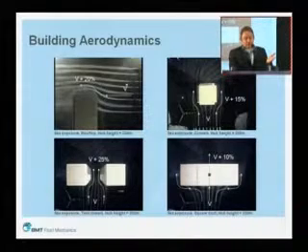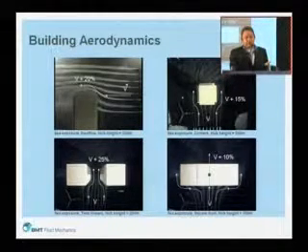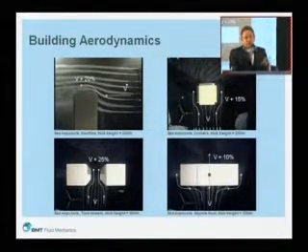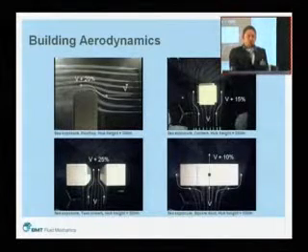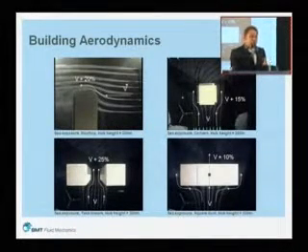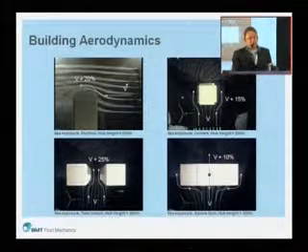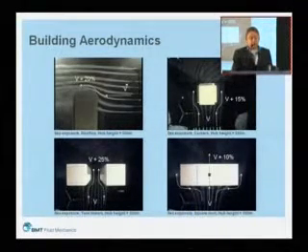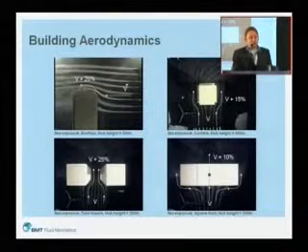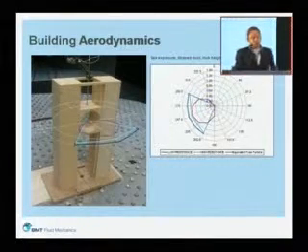You can have a ducted arrangement within a single tower, which generates funneling and increases the wind speed. Remembering that power is proportional to wind speed cubed, so small changes to available wind speed make potentially a big difference to power that's available to you.